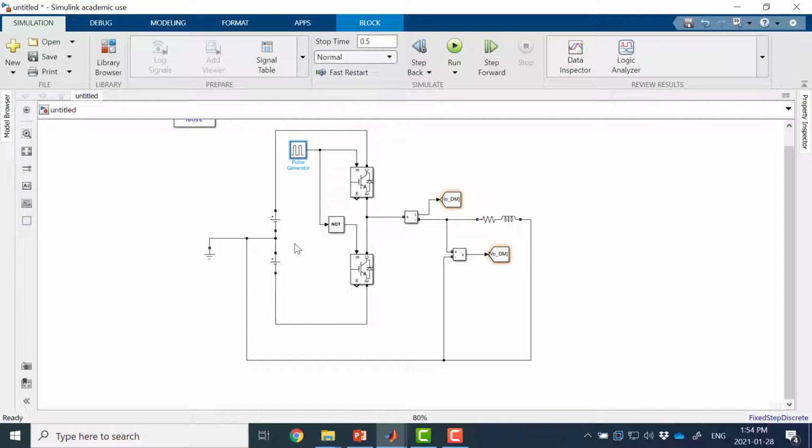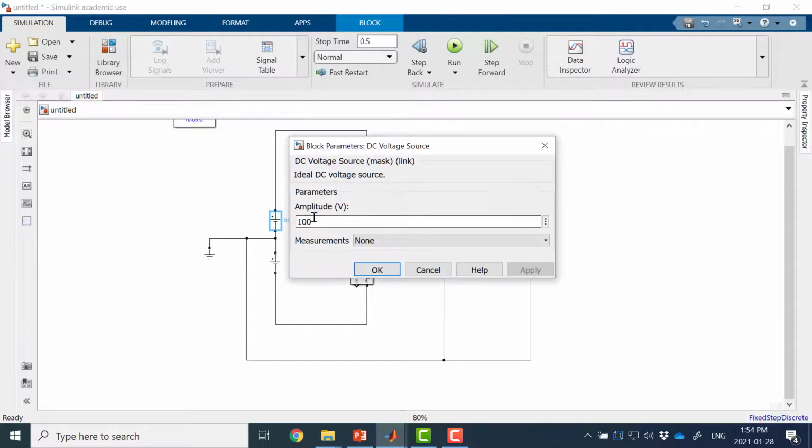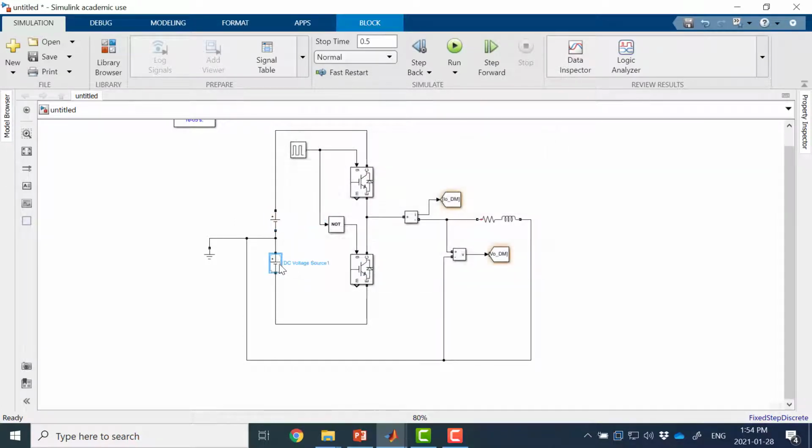In total, my DC voltage, VDC, my DC link is 100 plus 100, so I will have 200 volts in the VDC link, which is divided in half, 100 volts and 100 volts in series. So I will have VDC over 2 here. If I consider VDC as my pole-to-pole voltage from the DC side, I will have VDC over 2 for half cycle and negative VDC over 2 for the other half cycle.